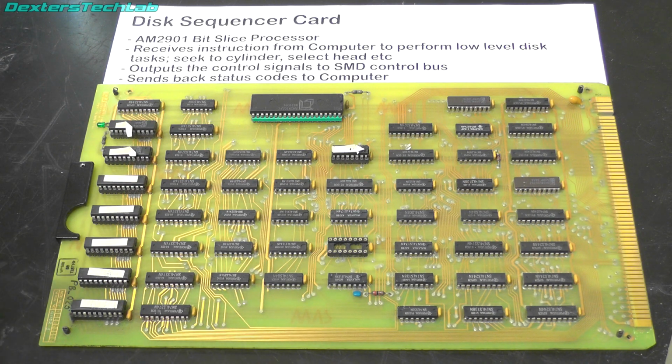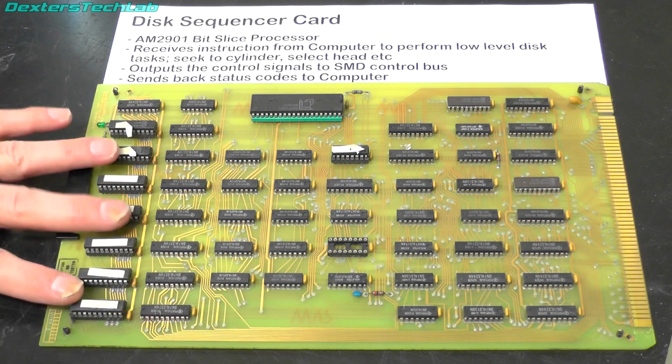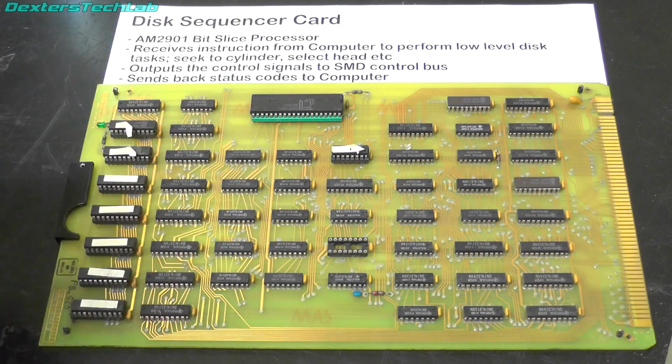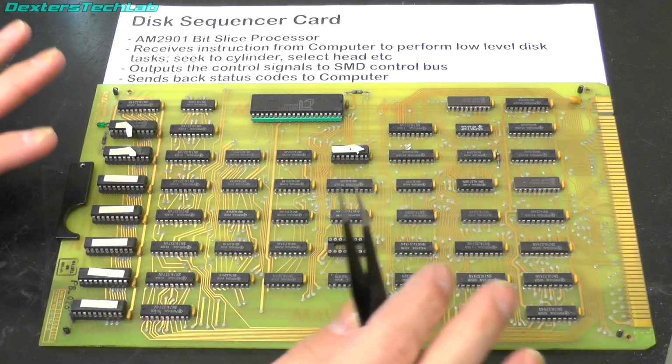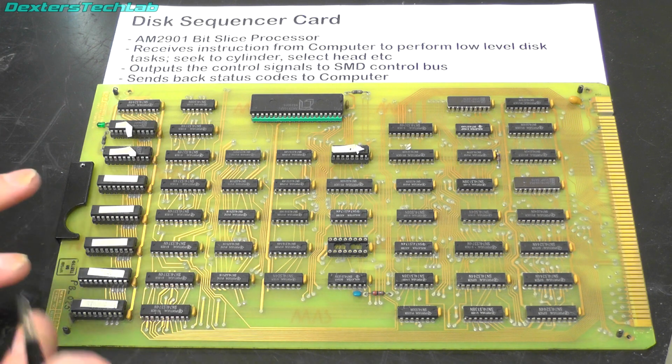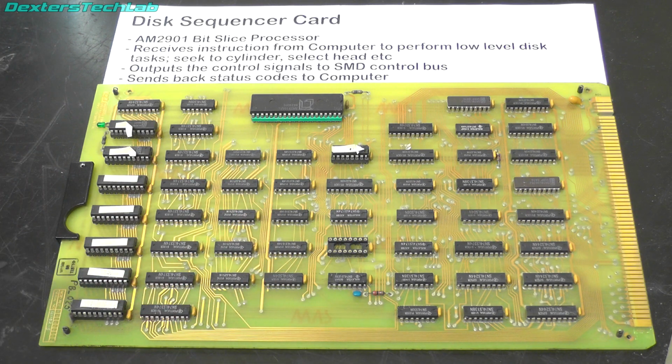But basically the way this works is there are 7 programmable ROMs on here which hold microcode for the 2901 processor. What this card does is it receives instructions from the computer card to perform low-level disk tasks. That might be seek to cylinder, select head. So this does all the stuff that is involved with moving the heads around, checking to see whether it's on cylinder, whether the drive is ready, that kind of thing. So a lot of the SMD control bus is actually operated through the disk sequencer card.